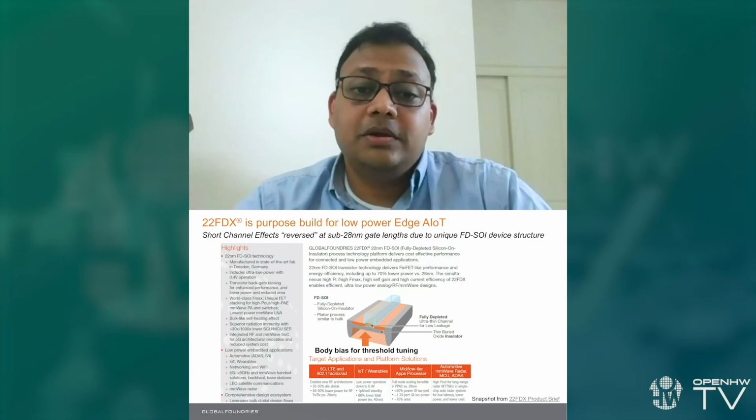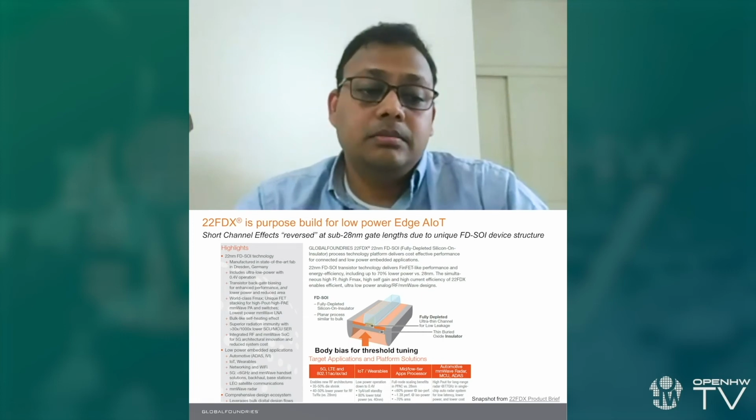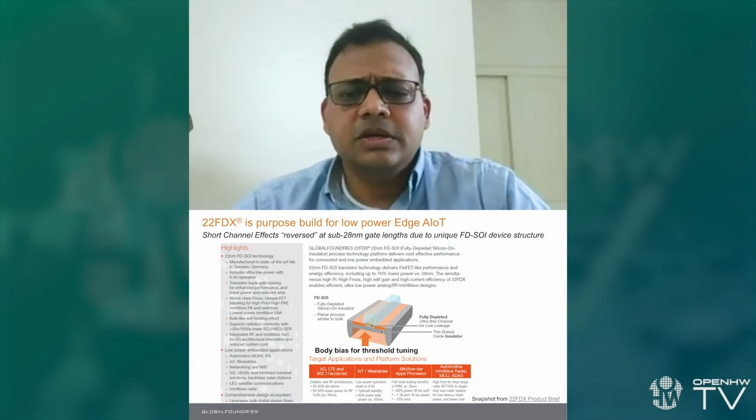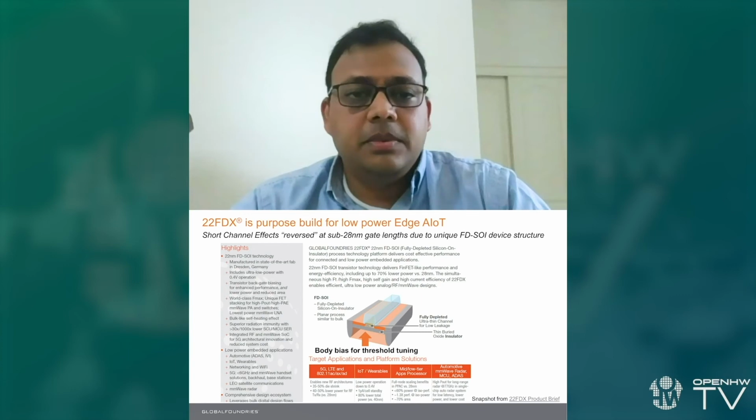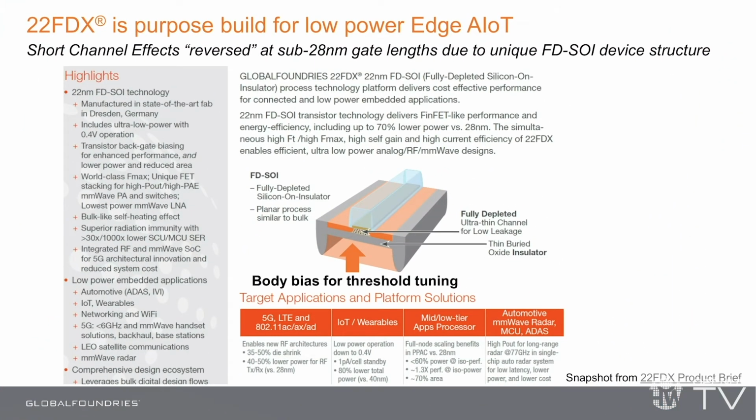So that is what it brings to the table. Not just that, but depending on your application and the mode where you are, dynamic or standby, you can actually have the advantage now of dynamically changing the threshold voltage to go higher speed or reduce the leakage when you're in standby. So overall, there are a lot of different benefits that we have with 22FDX. I cannot cover all of them, but I did include a link to the 22FDX product brief in this slide.